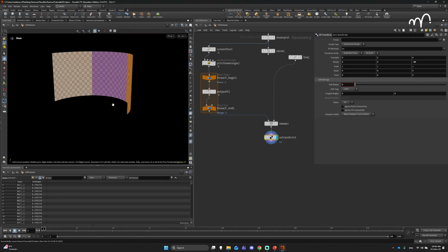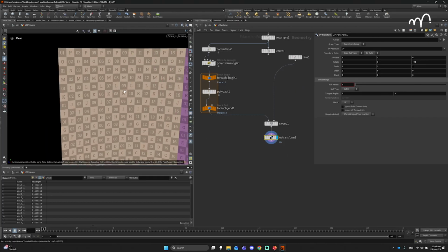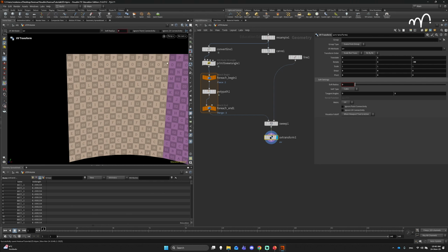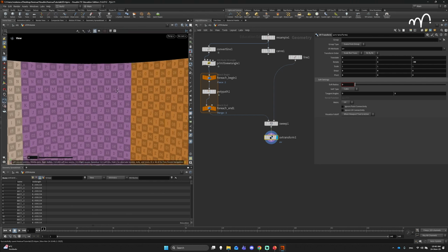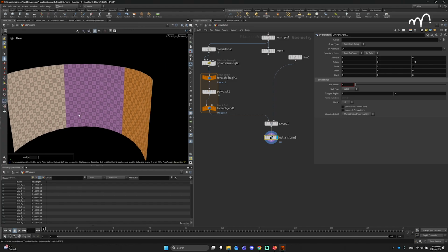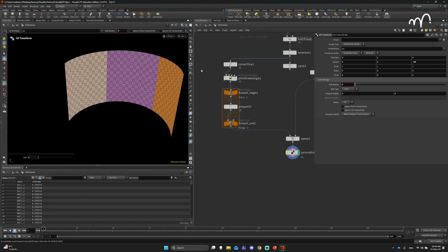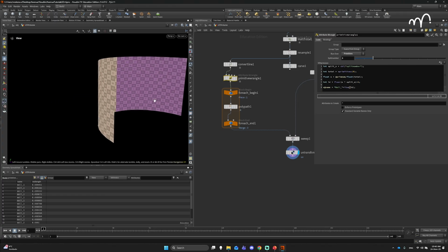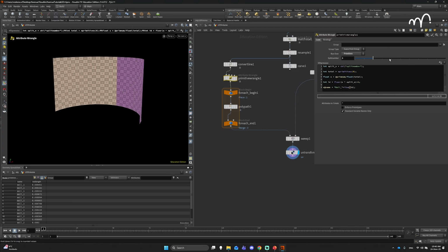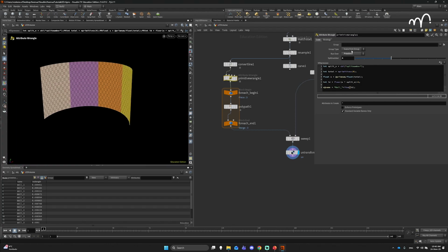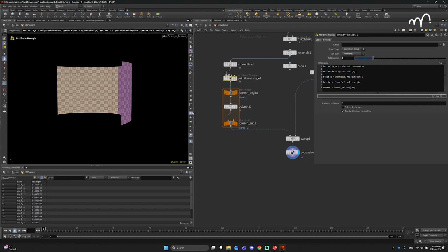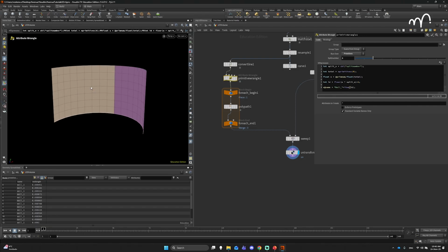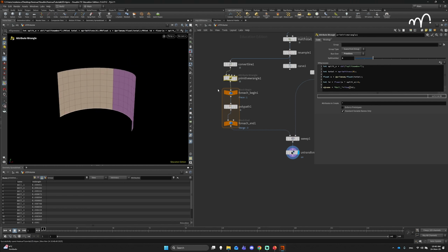If I go check my mesh now, you can see they're properly aligned and facing upwards. So 0 to 1 to P, and then 0, 1 P, 0, 1 P. So this is exactly the UVs that we want for our mesh itself once we import it into Unreal. If I split and make just 2 chunks of this, same logic still is applying. If we make 5, still same logic is applying. And this is perfect because the resolution of the grid is the exact resolution that we want. We're going to assign it later to the actual panel number and panel width and height. But for now, this is quite nice.